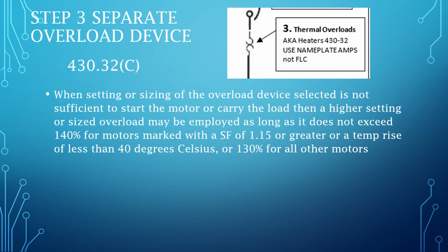As the motor comes up to speed, it may be drawing a much larger amperage than what the motor rating says that it is rated for. And so the wire can handle that for a very short period of time. We need a fuse or a breaker or a heater that for a very short period of time can handle that inrush so that it doesn't trip.